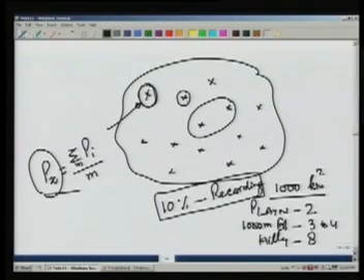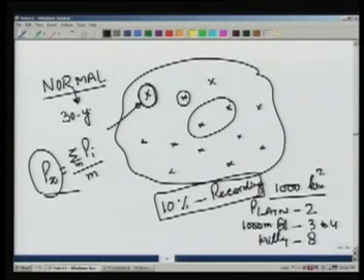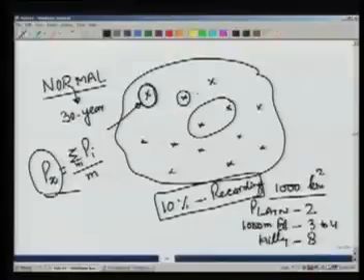So that's why we have to look at normal precipitation at various gauges. When we say normal precipitation, typically we say normal is taken as a 30-year average. So if we are looking at, let's say, May 18th, then we would consider what is the rainfall at those stations on May 18 over the past 30 years. And the average of those values would be called the normal precipitation for that rain gauge for that day.